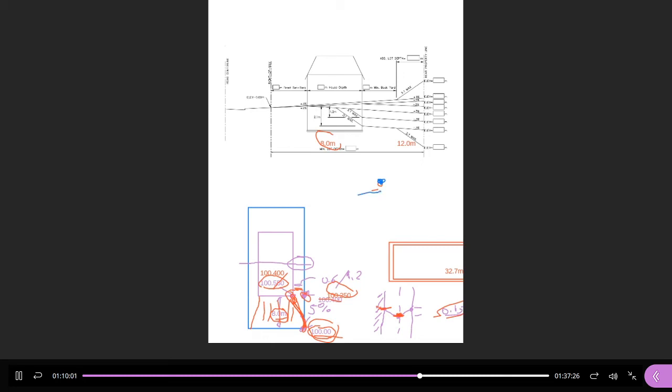One of them is going to work, and you're going to end up with a split point somewhere between the front and back of the building. The split point has to be between the front and the back of the building if you're in a split draining situation. Front drainer is the exception, obviously. So if you're between positive 0.15 and negative 0.58, you're going to have a simple split where the split point is either at the front, at the back, or somewhere in between the building, front and back. All right, so that's the scenario there.